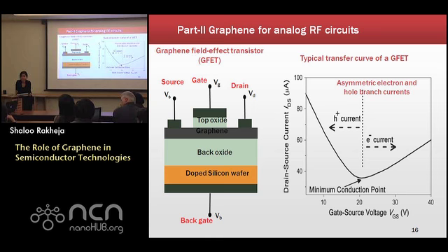Yes. It's very thin. So for graphene capacitance in these devices, when I published these results, we did not take quantum capacitance effects into account. We had only electrostatic effects, but we now have a full simulation that takes into account the capacitance between the layers, quantum capacitance and all those effects. But the conclusions are pretty much unchanged, that it has a lower capacitance.